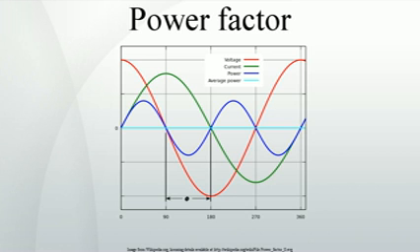The power factor of an AC electrical power system is defined as the ratio of the real power flowing to the load, to the apparent power in the circuit, and as a dimensionless number between -1 and 1. Real power is the capacity of the circuit for performing work in a particular time. Apparent power is the product of the current and voltage of the circuit.